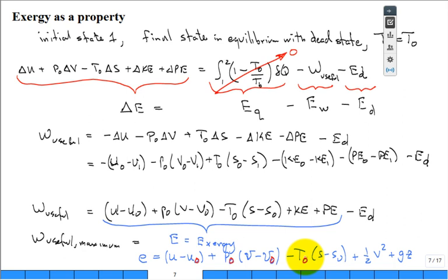Everything's referenced back to 25 C. What about the pressure? You think we should use 0 absolute pressure, like a complete vacuum? No, 1 atmosphere pressure. So this P naught is 1 atmosphere, T naught typically 25 C, but read the problem, they'll change it, make it a little different. Those are my exergetic reference dead state temperature and pressure.